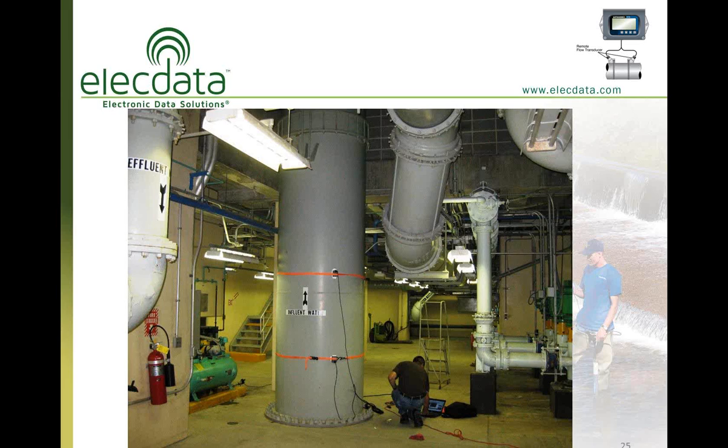The UTM10 flow meter is very small and can be used for portable or spot checking of pipes. So if you want to validate or verify flows from another flow meter, or to make flow measurements on pipes where there is no meter, it's a very portable system where you can just pack it in a toolbox or a Rubbermaid tote, move it around with you, strap the sensors to the pipe, plug it into a wall or into an inverter, or you may just want to have a small rechargeable battery in your tote with you that can be used to power the meter.